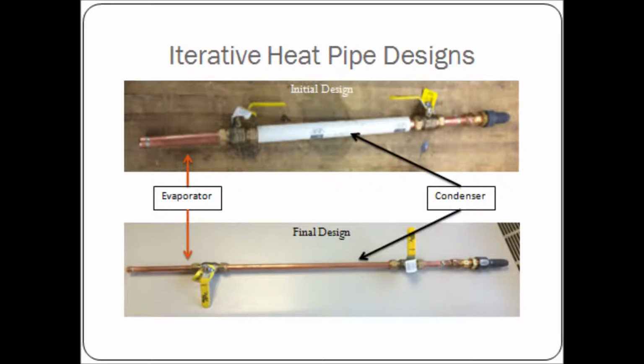Copper was selected for our heat pipe because of its high thermal conductivity, availability, and reasonable price. Distilled water was selected to be the working fluid of our pipe because the operating range of the water encompasses the operating range stipulated within the project requirements.